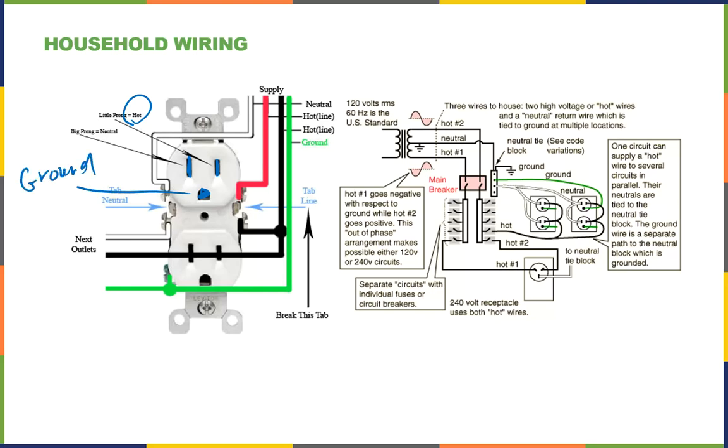So what's the difference in ground and neutral? Different pathways to the earth. The electric circuit is always supposed to be going between the hot wire and the neutral, and then you can connect that ground wire to things that a person might touch just to give them an extra layer of safety. So that's what those things are. That's why we have 3 wires, for safety.